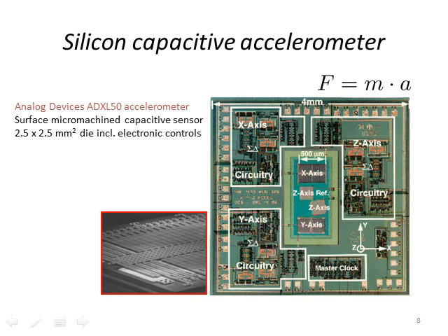And remember that that is 10 to the minus 12 meters. And remember atomic distances are on the order of angstroms, which is 10 to the minus 10 meters. So for a few euro, you can resolve displacements of those capacitance fingers that are smaller than atomic distances. Quite a powerful technique.